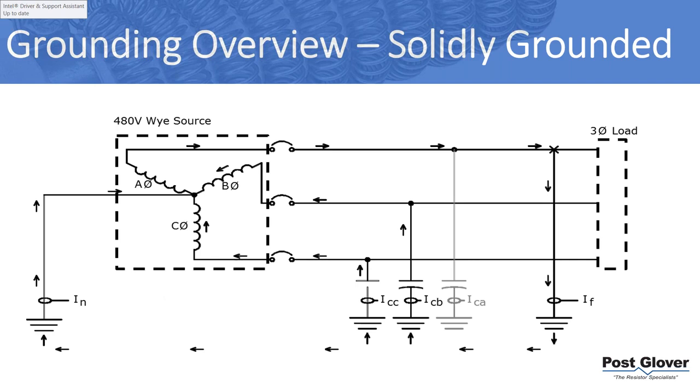In some ways, it's not good, because especially with larger systems, you have so much energy that sometimes you can't clear the fault fast enough without damage, without life-threatening potential events like arc flash, arc blast, etc. So that's the downside. The overcurrents essentially are the downside of solid ground systems.